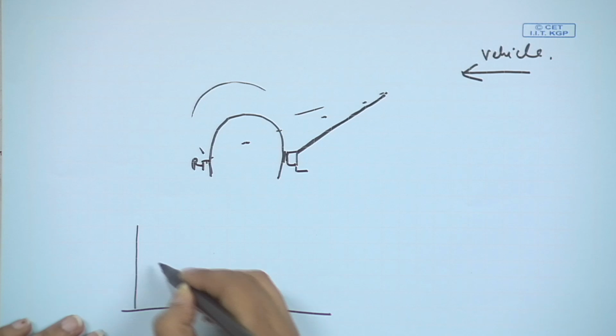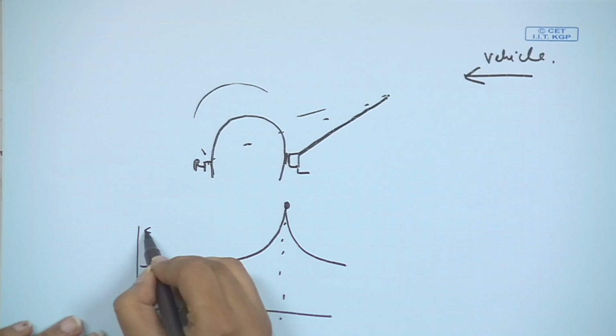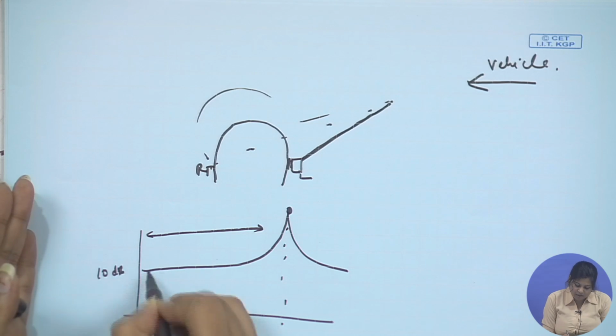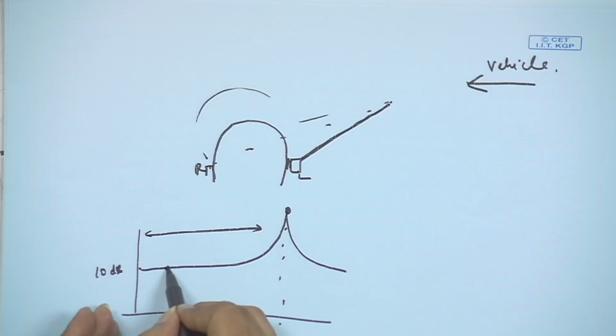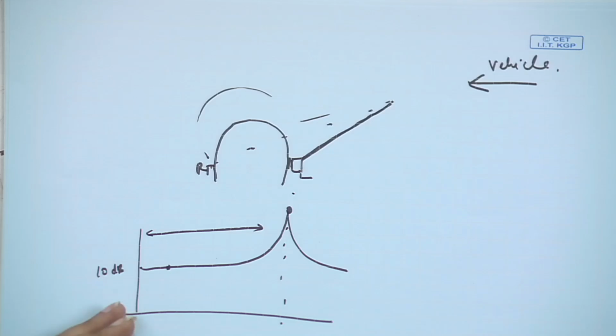And human hearing, as already pointed out in a previous lecture, is different: a microphone is a linear system, but the human ear is not. We studied that this is, for example, the response characteristic of a microphone, and this is the fundamental frequency, then usually this becomes the operating range where we have a flat response. So if a 10 dB sound is being recorded from the microphone, then it is recorded as 10 dB and not as a higher decibel, like 20 or 40, 70. So we want a flat linear response. Most of our transducers are designed to have a linear response, but our human ear does not.